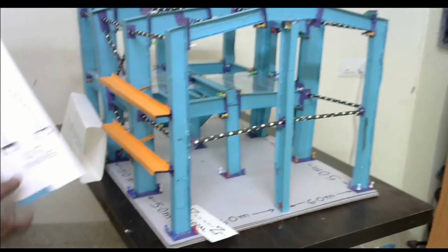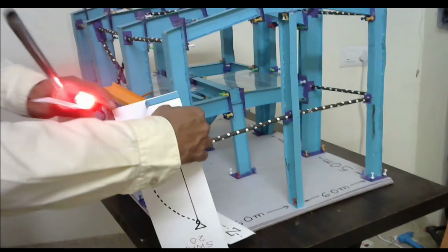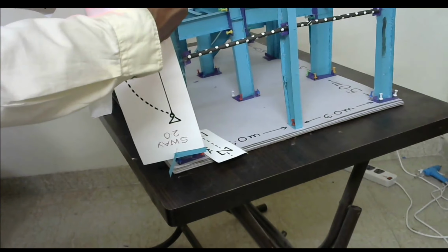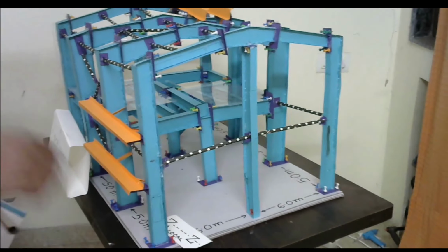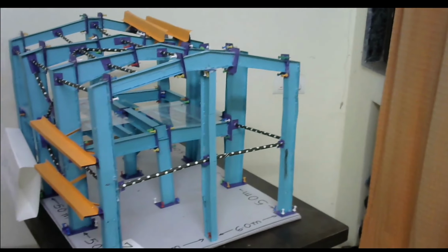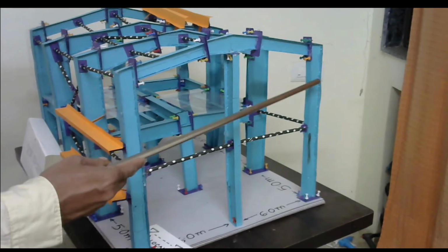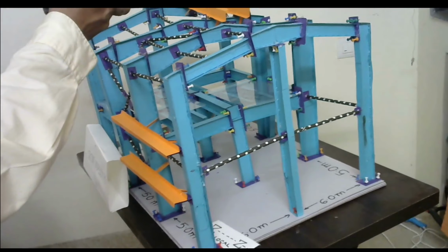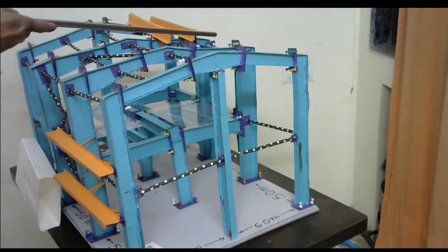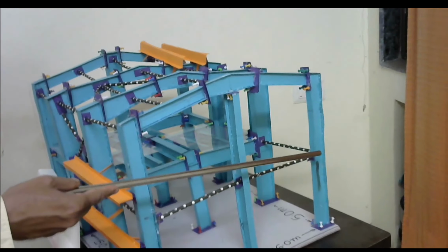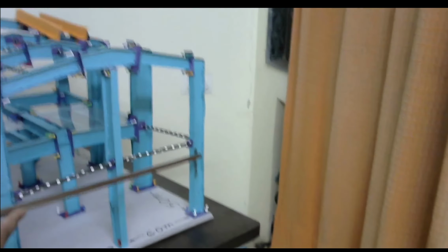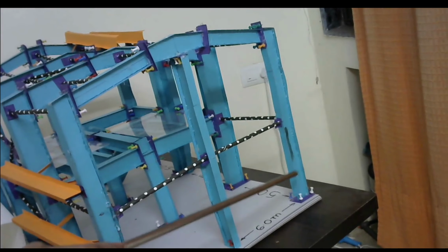Again for this column, our usual portal case comes. Bottom pinned, top fixed. So the same will be the case here for this column. There is a portal brace here. I told you portal brace itself will be considered as a sway frame, but for the other part we can consider they are the non-sway columns. They are basically gravity columns about these directions.